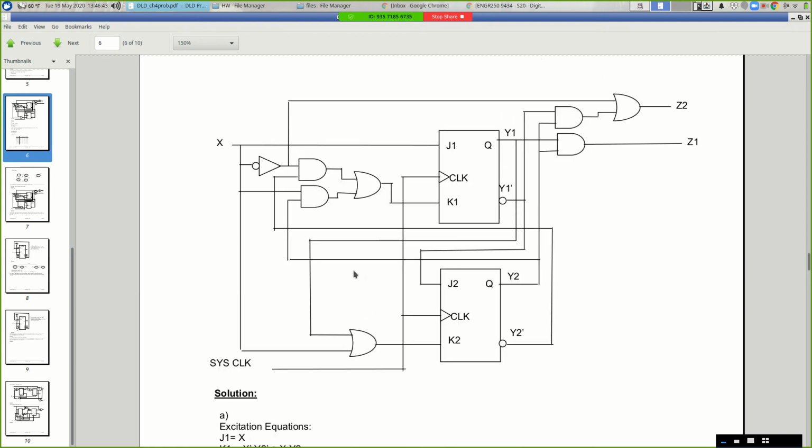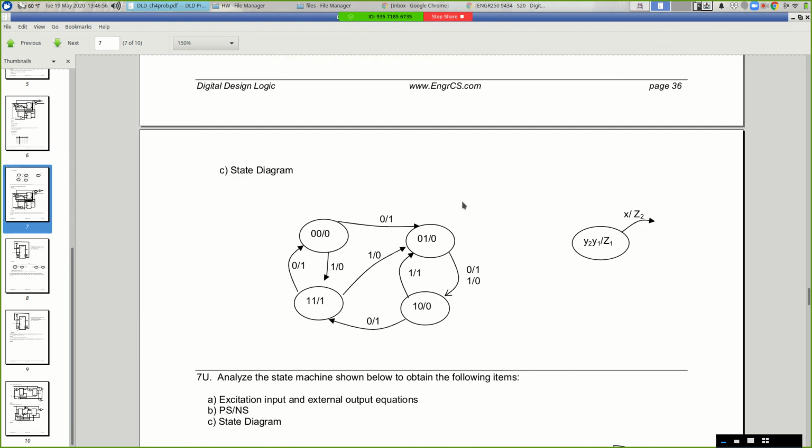like this. And we're not going to describe the circuitry by saying, you know, take an inverter and an AND gate and send the output to an OR gate and send that to a flip-flop, right? We can do that in Verilog, but we can also do things like, I want a circuit that, when I'm in state 0 and the input is 0, moves to state 1. And we can code that up with like a case statement or a bunch of if statements. And Verilog is a really fun way to design and implement digital logic, and it's very different from what we've been doing, but you have to understand what we've been doing to be able to write Verilog, okay?